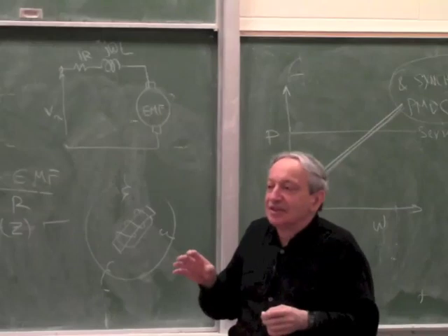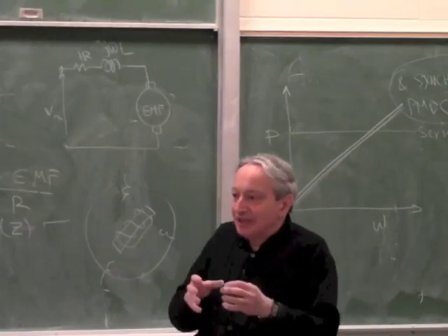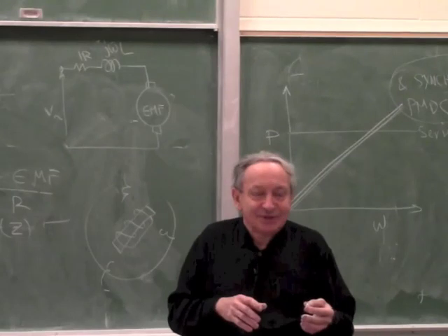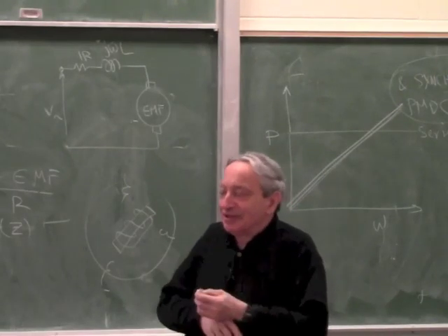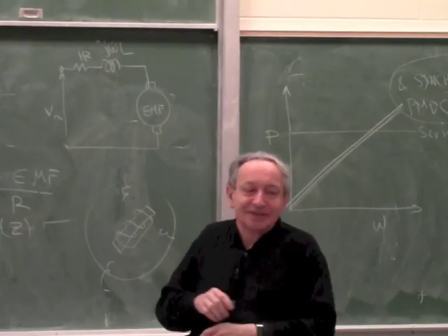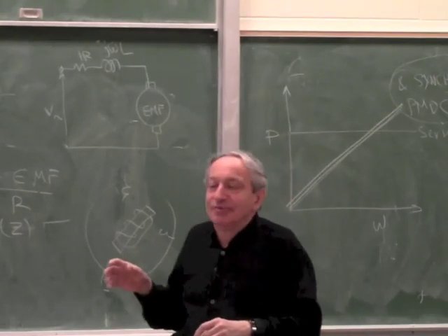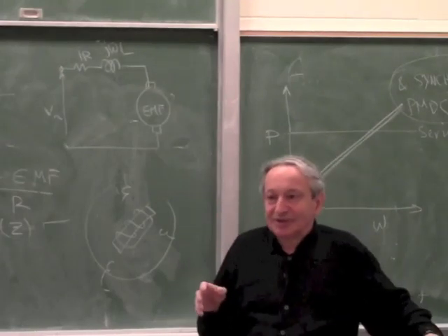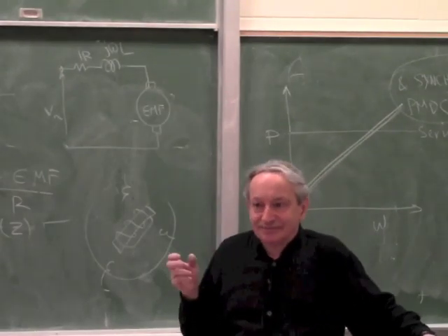That is exactly the reason why cars used to have a dynamo with brushes and got replaced by an alternator, which has slip rings but no sparking. Because the slip rings are continuous, they don't interrupt the current, so there is no sparking. That was a huge improvement, putting alternators instead of dynamos in cars, because there's nothing to wear. Okay?